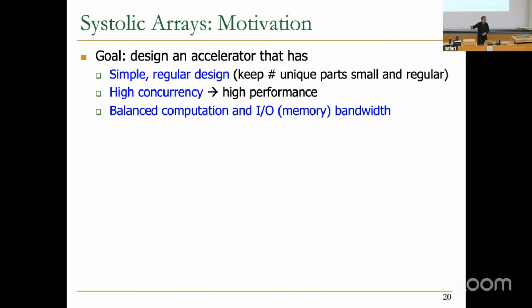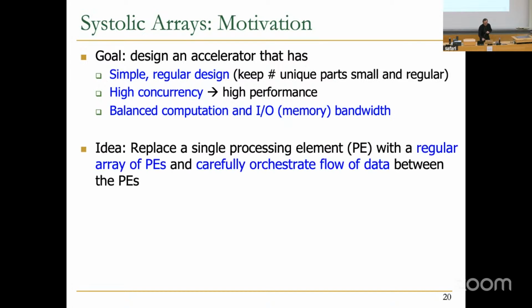Kung realized, and he did a lot of work on this topic, and this is one of the reasons why we work on processing in memory as well. But he said that if you have a processor that just keeps doing load, store, load, store, load, store, you're not balanced. Meaning you have a lot of computation power in the processor, but memory is very slow and has low bandwidth. So you're basically bottlenecked by memory. So let me design a hardware accelerator that's not bottlenecked by memory, or balances the computation bandwidth and the memory bandwidth. And we will see that in a picture.